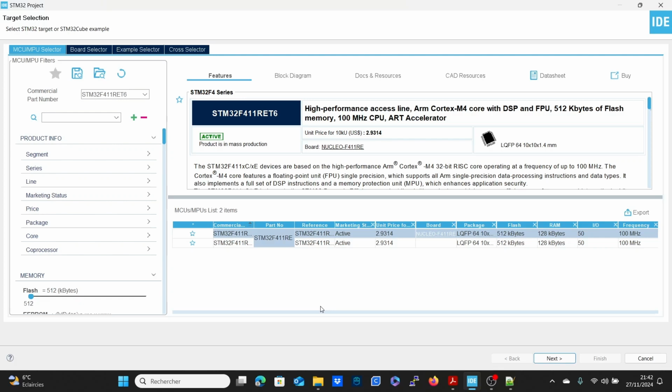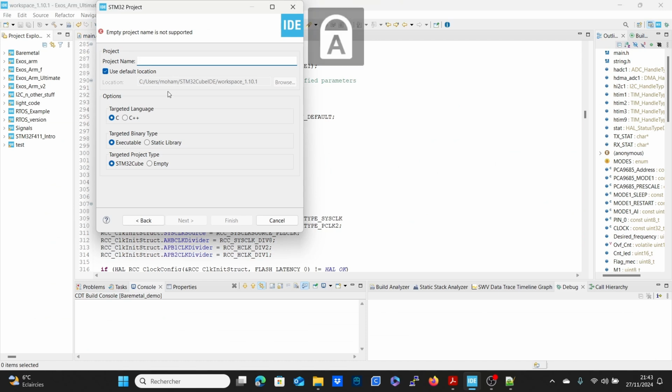Hello guys, welcome. In today's video, I'm going to show you how to program an STM32 only using registers. So right here, I'm going to select my STM32 F411 and create a project for that. So let's call that Bare Metal demonstration. And here I'm going to choose an empty project so that I don't have all the HAL libraries auto-generated.